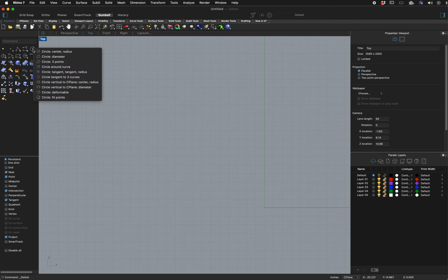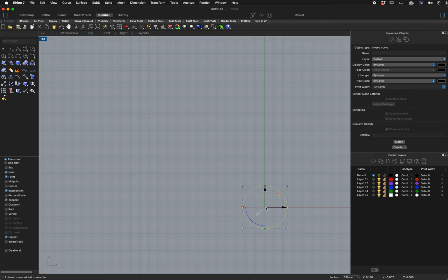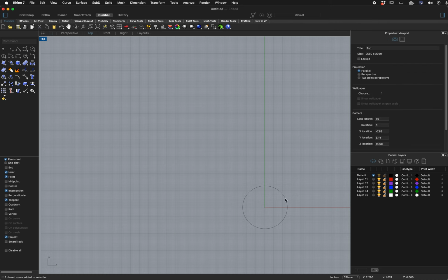You also have some basic sort of drawing tools. So here's a circle tool. And so, again, similar. If we set the position here, we can also, again, to be precise, go here to the radius and give it a radius of 2.5, which is 2.5 inches. Hit return. So now we have a circle that has a 2.5 inch radius, so it's a 5-inch wide circle.